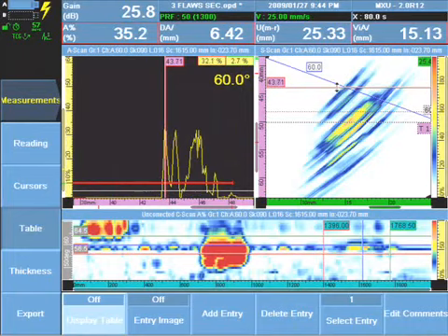Where we have identified the deepest ligament of the crack at 6.42 millimeters deep from the outside surface at a position of 15 millimeters. This is the volumetric position on the index axis, or the position in and out of the weld for the signal in gate A. And we will record the associated information into the table as well.